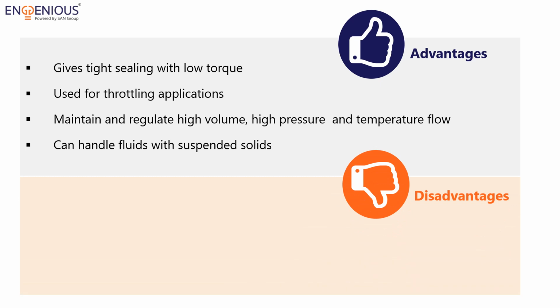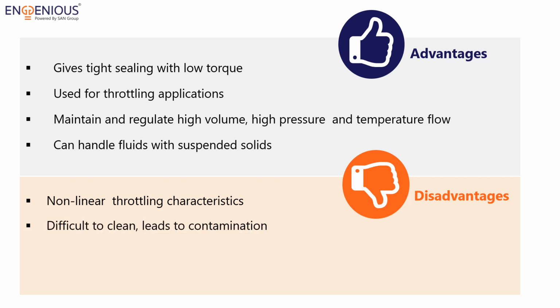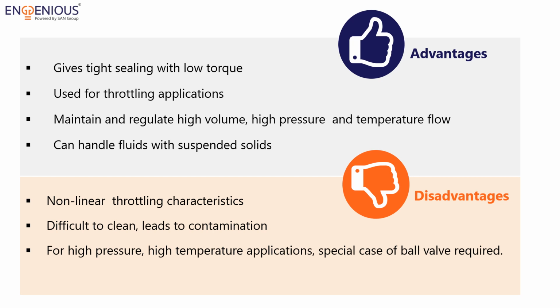Disadvantages of using ball valve. Ball valve has nonlinear throttling characteristics. It is difficult to clean, which then leads to contamination. For high pressure, high temperature applications, special case of ball valve required, which in turn increases cost.